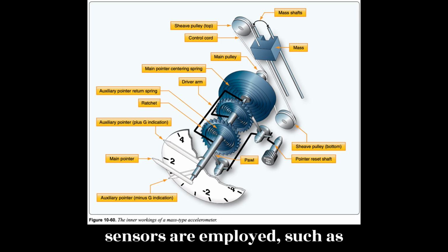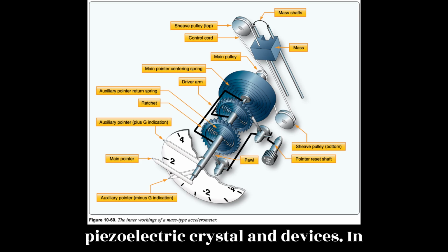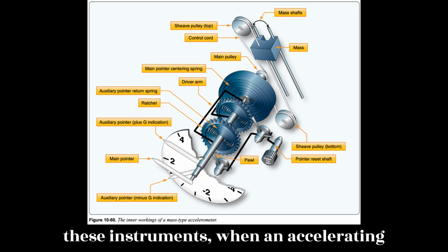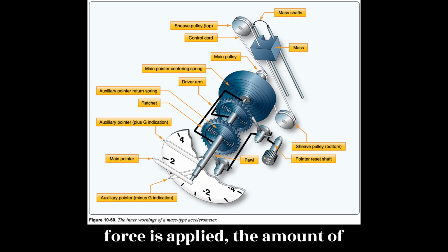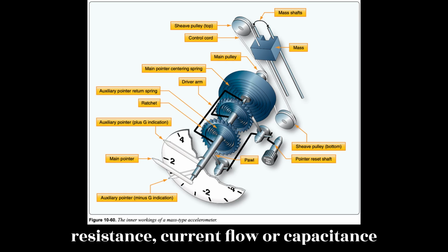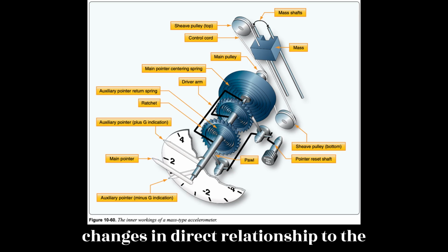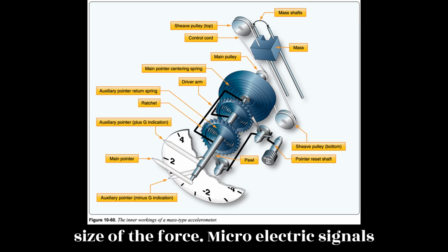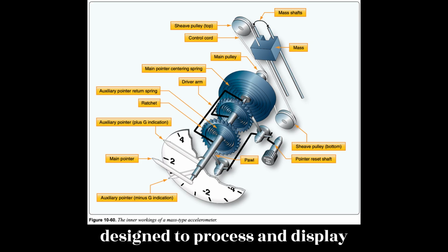Solid-state sensors are employed, such as piezoelectric crystalline devices. In these instruments, when an accelerating force is applied, the amount of resistance, current flow, or capacitance changes in direct relationship to the size of the force. Microelectric signals integrate well with digital computers designed to process and display information in the flight deck.